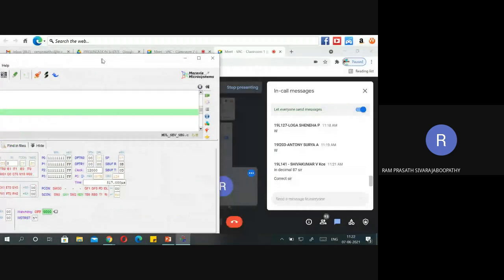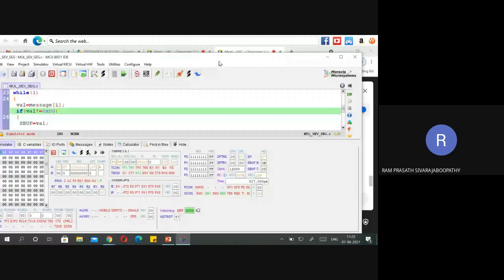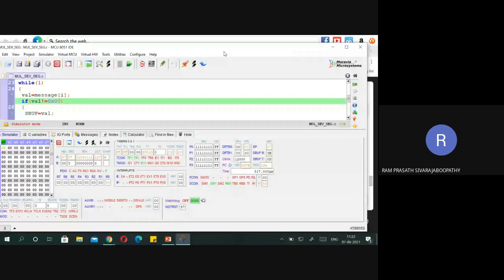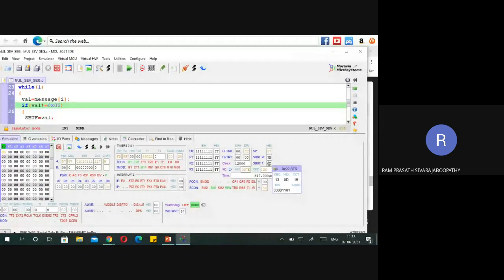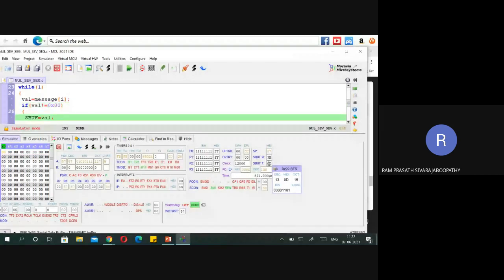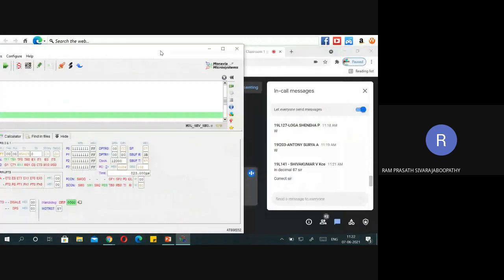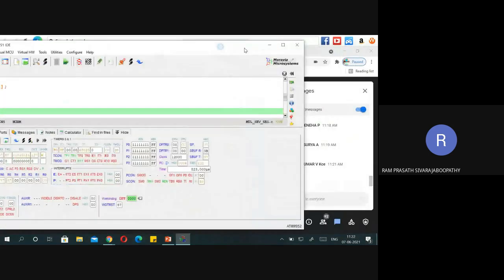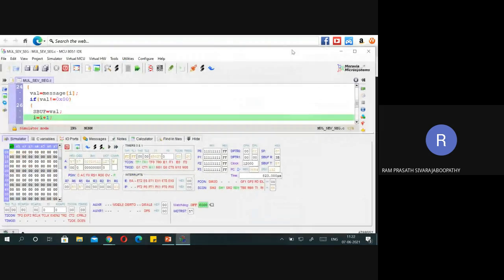Yes, fine. So now that value is not equal to null, correct? So where does it have to be written? It has to be written into the SBUF transmit. Now it is having 0D. Please listen. Yes, val not equal to null. Is it loaded now? In SBUF, you can see the data now. If it is not equal to null, it comes here. Correct. Fine. So next step.